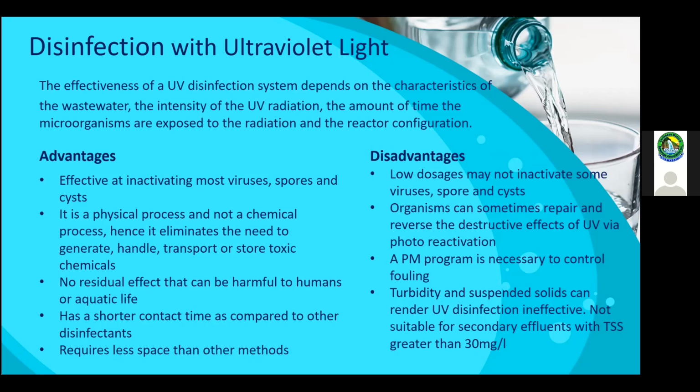UV light is effective in inactivating most viruses, spores, and cysts. It is a physical process and not a chemical process. Hence, it eliminates the need to generate, handle, transport, or store any toxic chemicals.